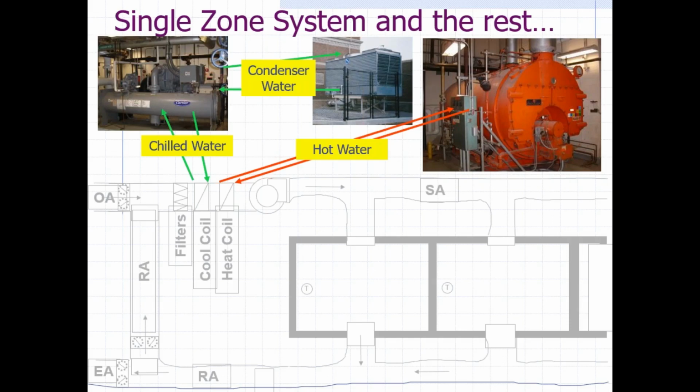they call it cooling tower fill. I don't have a picture of it, but it just drips the water. You've seen it, and then the fans run, and what it does is cause evaporation, and when things evaporate, it cools things down. I think you know the feeling, having gotten out of a swimming pool and you stand outside and you get really cold. It's because when the water's evaporating off your body, it's taking all this heat out of you. And that's exactly what happens in a cooling tower. So then the water is cycling through the cooling tower back into the chiller, and that removes the heat that the chiller is removing from the cooling coil.